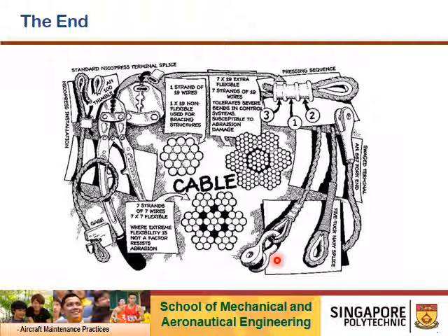So in case the computer fails, or there's no electrical power on the aircraft while it's flying, you have a mechanical means that requires no electrical source or power to move the flight control surfaces. So you still need to have a mechanical control between the cockpit control columns and the primary flight control surfaces to allow roll, yaw, and pitch when the whole fly-by-wire system fails.